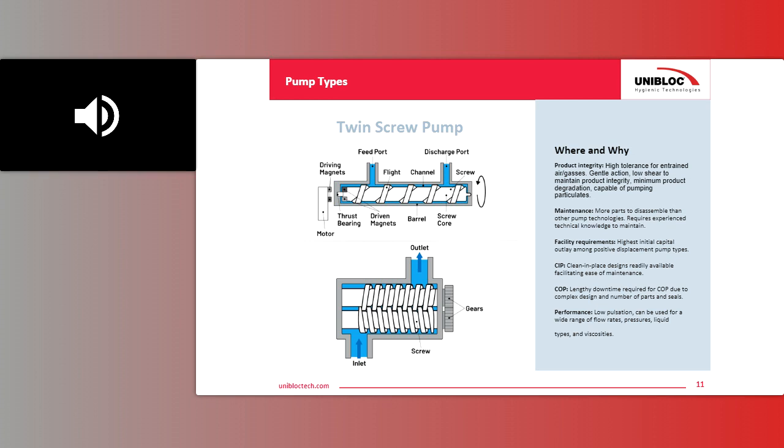On the maintenance side, it can be more involved, taking it apart and putting it together, which also adds to the time-consuming part if you're going to COP, or clean, this pump out of place. So traditionally, these pumps are used for clean-in-place applications as well, because it's time-consuming to take them apart.